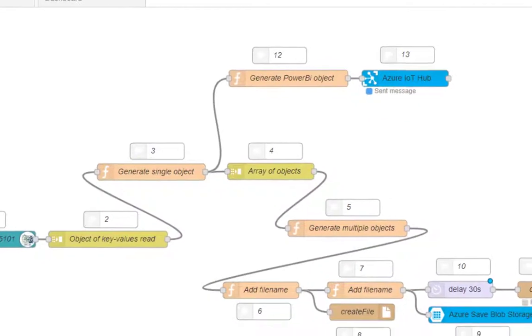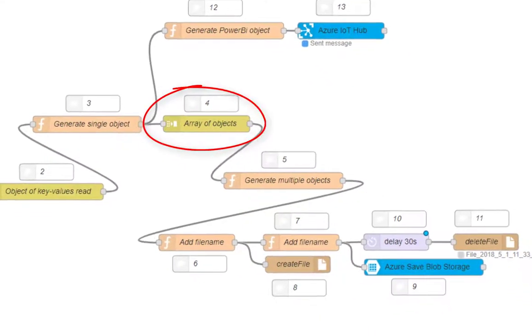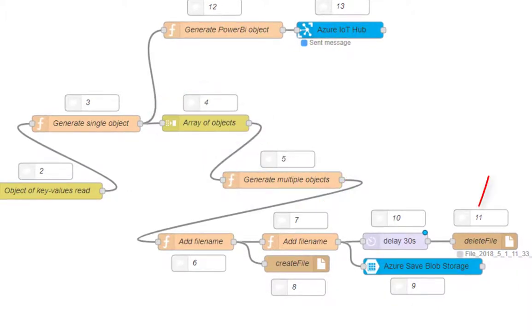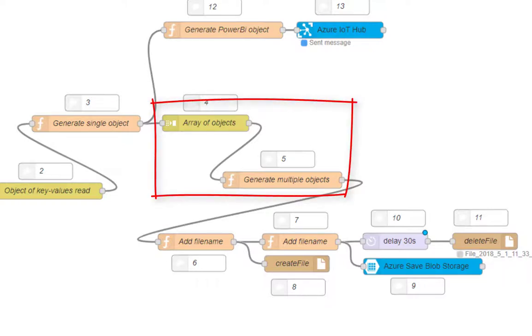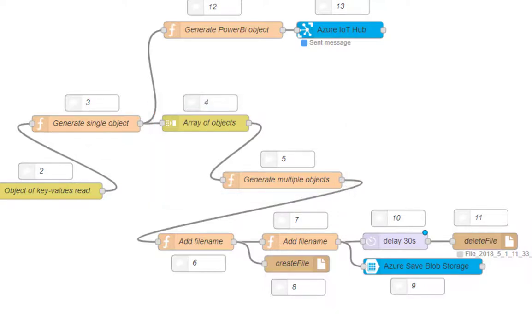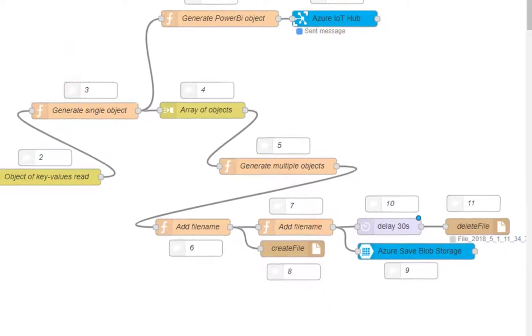The second task collects 10 samplings of data in a single JSON message and sends it into the Azure Blob storage. The reason why the stored message contains multiple data is because of the limitation of the student's account of 8,000 messages per day. The files are named using a timestamp as a string to avoid overwriting. In order not to overfill the netPi, the files are deleted after some time. The messages sent in both steps to Azure must have the desired header in JSON format.